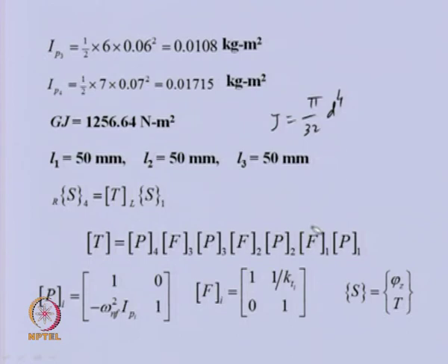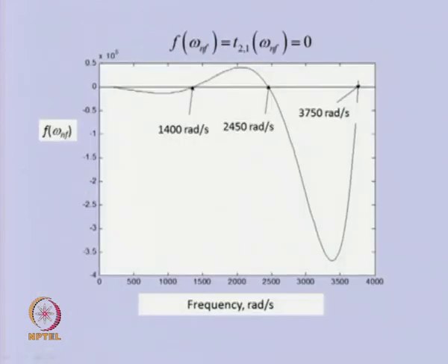So, in this particular field you can see there are so many point and field matrices getting multiplied, point matrix and field matrix, as here we are not considering damping, but only the stiffness properties and the inertia properties are there. So, you can see that this is the overall transfer matrix, and free boundary conditions are there.